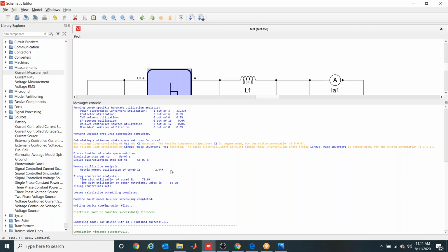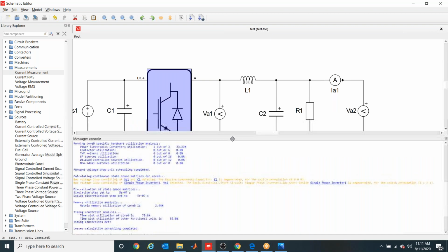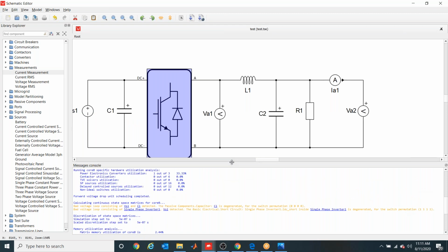Actually, this is about what you are talking about right now. In this model, the controller is not used, first thing. Second thing, the placing of components, where you want to place the particular components. The position and situation both are going to affect the converter switch voltages. I think this is the single phase inverter model. If you draw the truth table, you will get 0001 and then 1010, and so on. If you count the number of state space matrices which are going to form, this model having 4 switches, there are going to be 2 to the power 4 state space matrices formed. Accordingly, which matrix combination is going to be affected by not having the particular component position is shown here. Right now this is just a warning. This is not going to affect your modeling or anything else. I hope you got the answer.